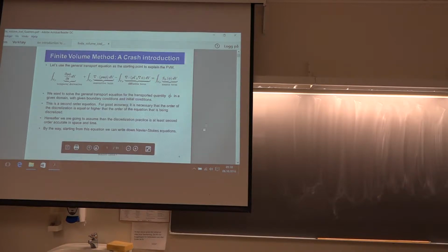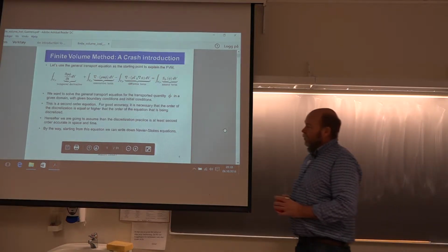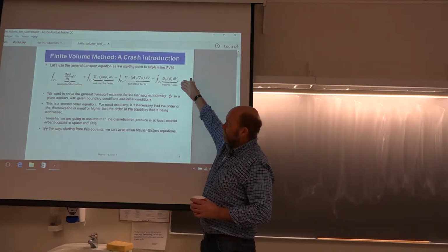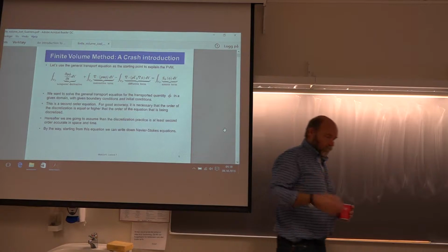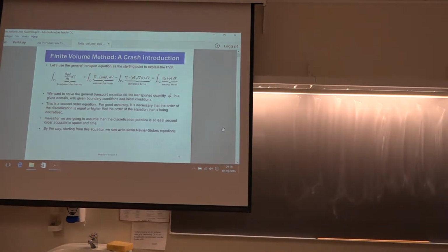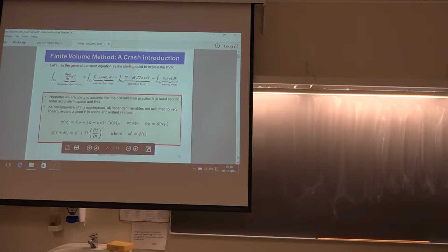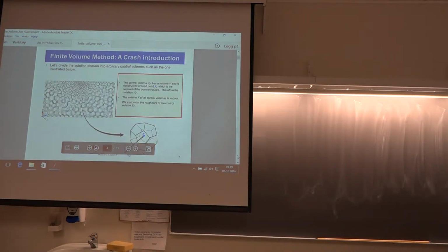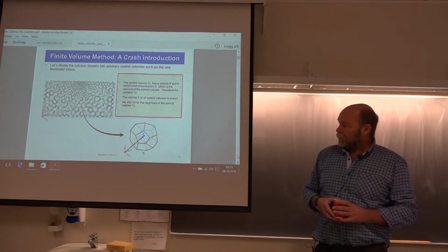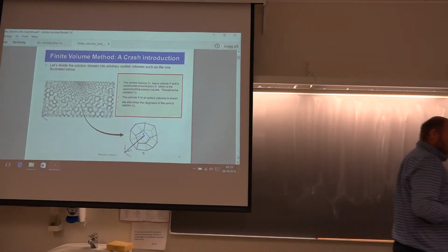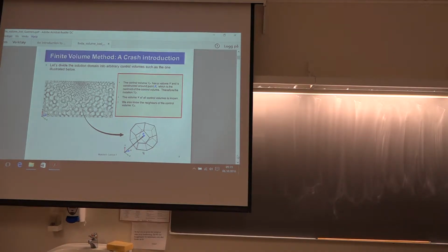I'll just go through them a little bit quick. So this is sort of the initial equation, the place to start, the original: a volume integral over your finite volume. What we do is discretize our space into nice little volumes, and the volumes, as we now know, have to be convex, but they can have any number of faces.